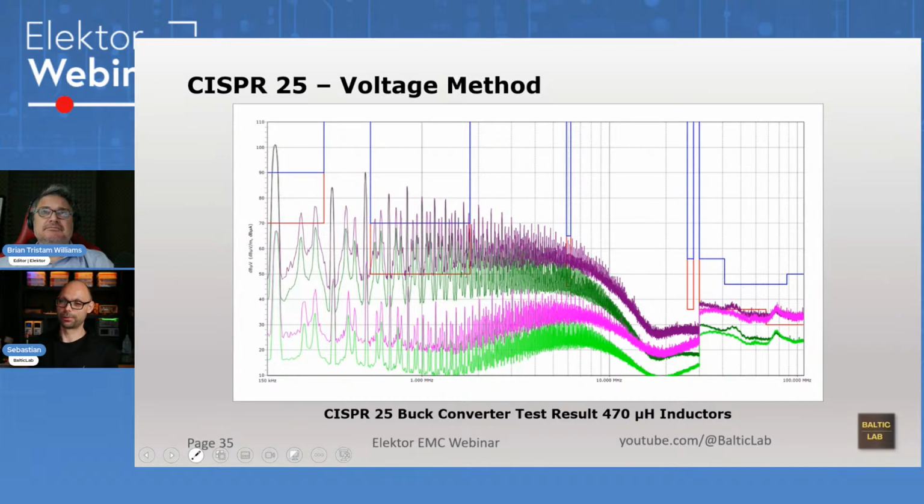I wish I would have recorded it, but this switcher, for instance, has a switching frequency of 50 kilohertz. We don't even see how horrible it is there, because we technically don't care. But on the 50 hertz, there are harmonics that happen, which are very important to take into consideration. And also, just as important, your mains power isn't as clean as you might hope. If you would plug some sort of measurement converter into your wall outlet, you would probably need therapy afterwards. It's horrible what kind of nasty stuff comes out of there. So yes, you need to take that into consideration.